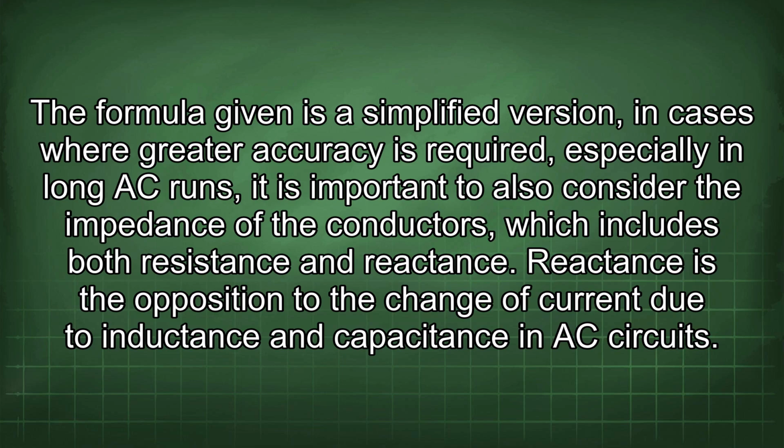In cases where greater accuracy is required, especially in long AC runs, it is important to also consider the impedance of the conductors, which includes both resistance and reactance. Reactance is the opposition to the change of current due to inductance and capacitance in AC circuits.